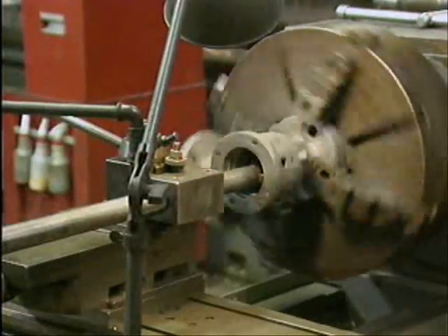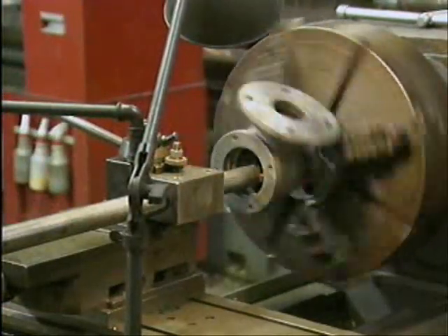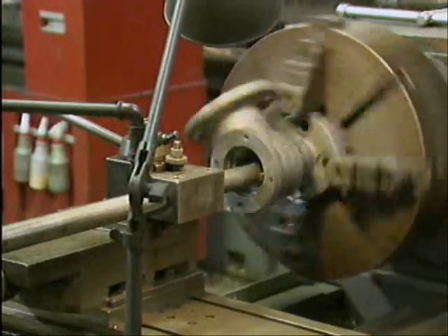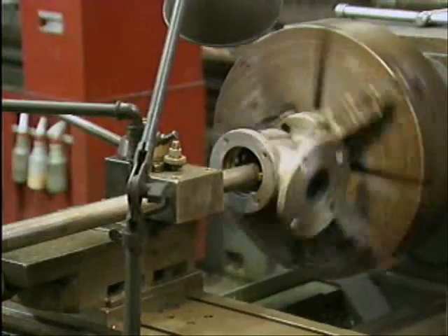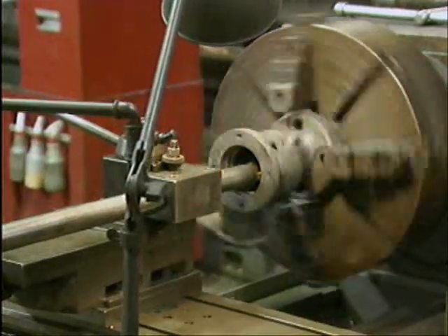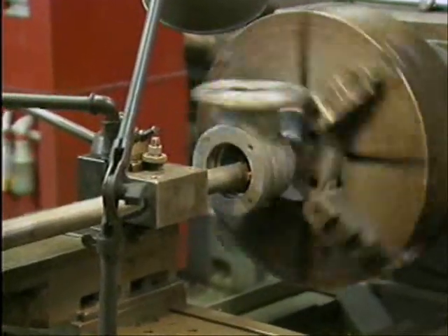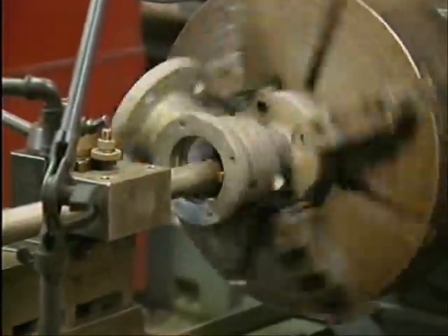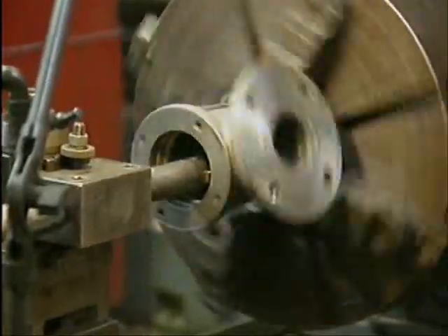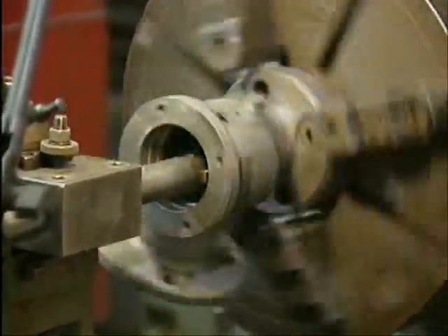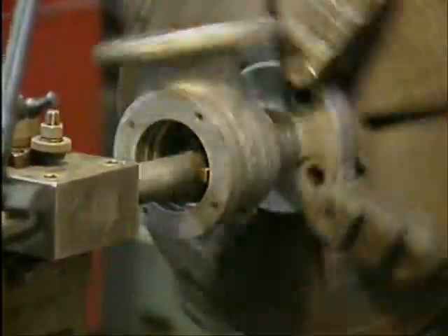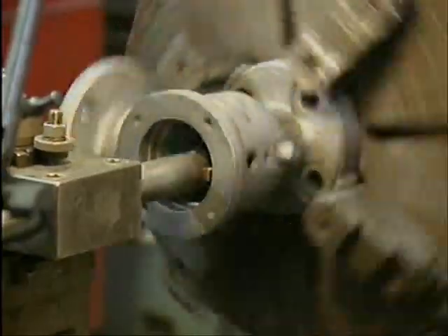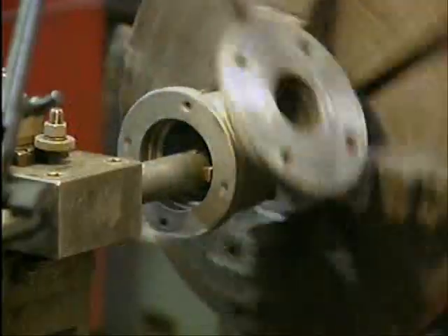A valve seat may, however, be so severely damaged that you can't restore its surface by lapping. If the seat is a permanent part of the valve body, you can often use a reseating tool that's specifically designed to restore the damaged surface, or, as in this case, you can mount the valve in a lathe and remachine the seat. However, keep in mind that extensive maintenance on a valve seat may also affect other valve components and valve specifications, such as the lift.